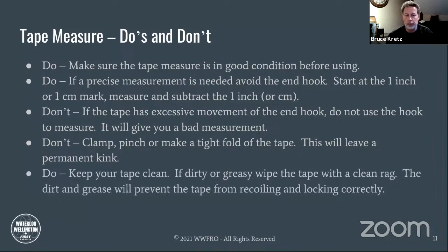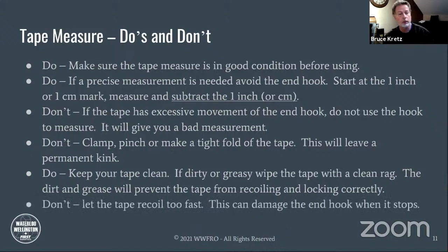Do keep your tape clean. If it gets dirty or greasy, wipe the tape with a clean rag before it goes back into the case. The dirt and grease will prevent the tape from recoiling and locking correctly. Try not to let the tape recoil too fast. This can damage the end hook when it stops suddenly, when it ends the recoil.